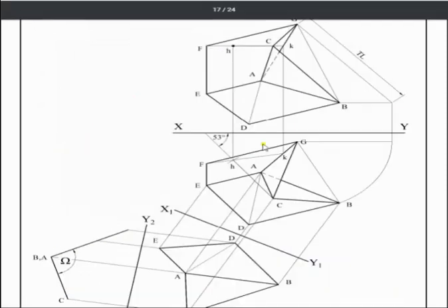So what we're looking at here is our line from C brought horizontal across. It's given us this point F here, and F happens to be the same height as C in this case. So we have the line drawn up here, we have this line drawn here, and then from C, scribe our arc 55. So that's given us our horizontal line now.